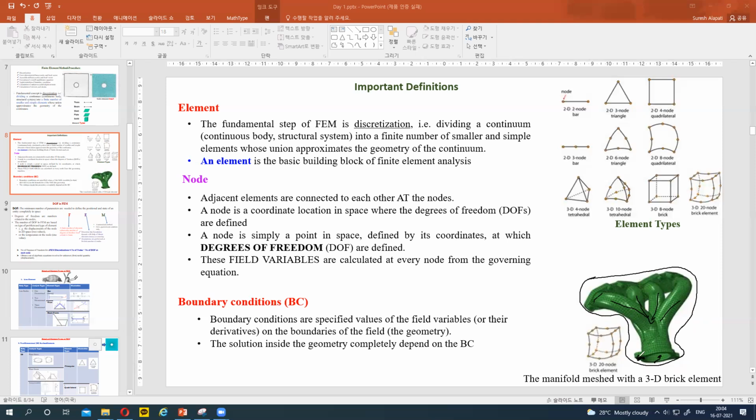There must be some boundary condition because we are connecting using bolt and nut, right? So here we fix this one. That is the boundary condition. Similarly, this body is connected to another body, so based on that body we have some other boundary conditions, maybe fixed or something.